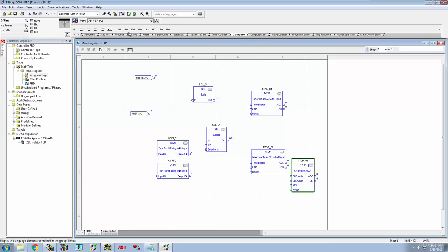We've got comparison. We always use our equal tos. We've got our equal to right here, limit. If we want to test and make sure that one value is between two others, if I could get this thing selected and pull it out of the way, it just does not want to move for me, does it? Yeah, here we go. We pull in our test value right here. We've got a low limit and a high limit that we want to test and make sure it's between. And assuming that it is, here's our output that we can shoot out from there.